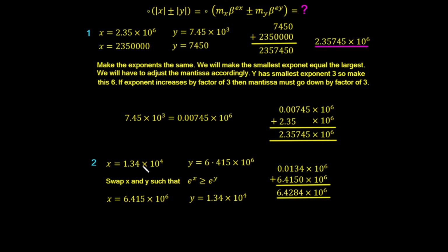So that would mean that if we were to realise this in an actual circuit, we would have to swap the values for our x and the y, because the circuitry that we would have access to and designed will make the exponent larger and the mantissa smaller. And in order to get the right answer, we would have to therefore ensure that we were using this value here. This would be making the exponent of x larger and the mantissa of x smaller.